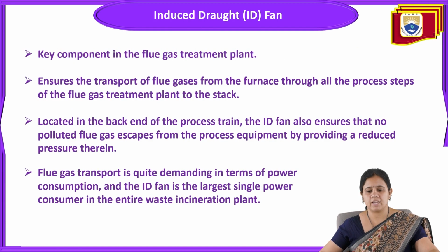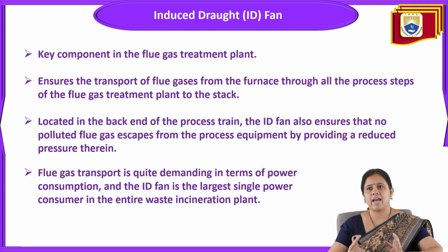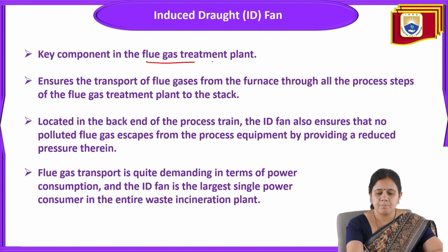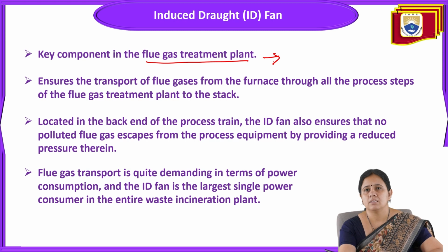Now comes the induced draft fan. First of all, a fan called the induced draft fan, ID fan, is installed. This is the main component in the flue gas treatment plant, and it ensures the transport of flue gas from the furnace through all the process steps of the flue gas treatment plant to the stack.